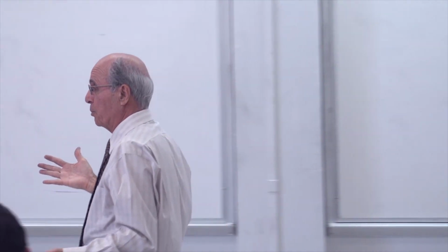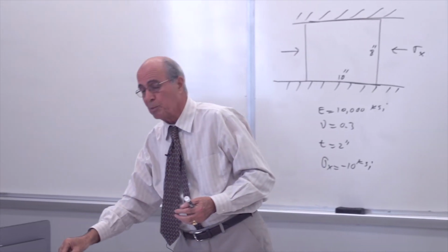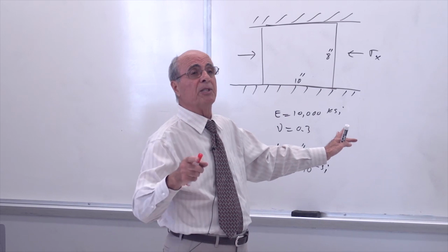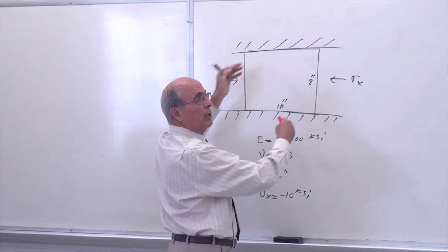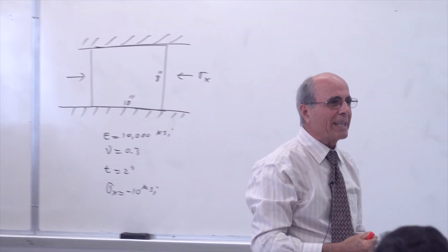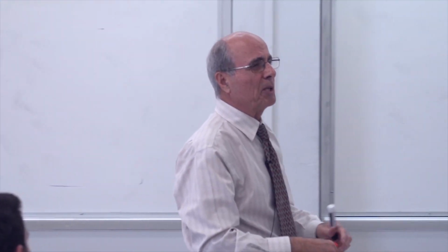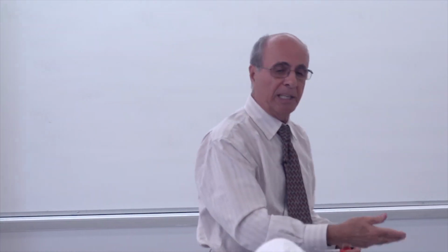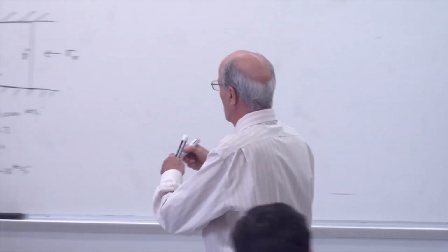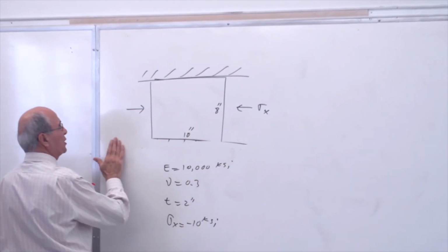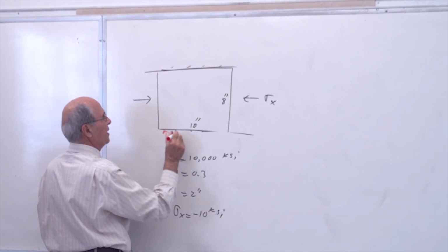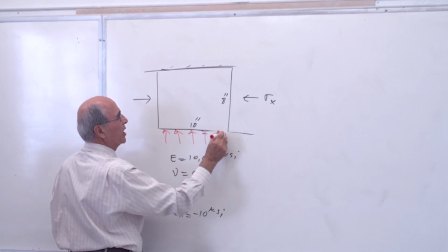So you can use even superposition method. But I do not suggest superposition because superposition is long. I have given this problem exactly as a quiz, and some students did that. They remove this wall, they let it expand, then with the force they push it back. So that's the sigma. Is the force over area becomes sigma. But I'm showing you a better technique with the E. Is that understood? Yes? You can do that. But there is another one. We already know that the effect of this, we have to remove that, by the way. The effect of this and that is a sigma going this way. Is that correct or not? Yep.